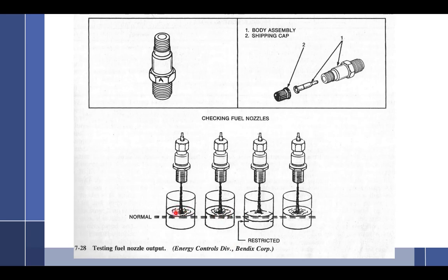So you'll see most mechanics in general aviation have 6 little cups that are all about the same size. And yeah, they say baby bottles. Plastic doesn't work as well with fuel as you think. But anyway, all you do is take out all the fuel nozzles from all the cylinders. And they're connected. You can see they're already connected here to the little lines. And you just going to flow some fuel through it. All right, super mechanics, how am I going to get fuel to come out of those nozzles?